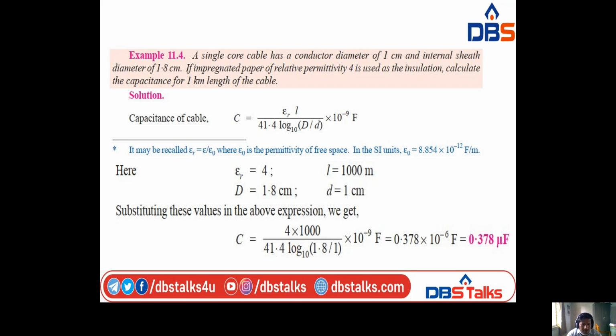C is equal to 4 into 1000 by 41.4 into log 1.8 by 1 base 10 into 10 power minus 9 farad. Therefore, capacitance is equal to 0.378 into 10 power minus 6 farad, otherwise 0.378 microfarad. Like this, we have to calculate the capacitance of a single core cable.